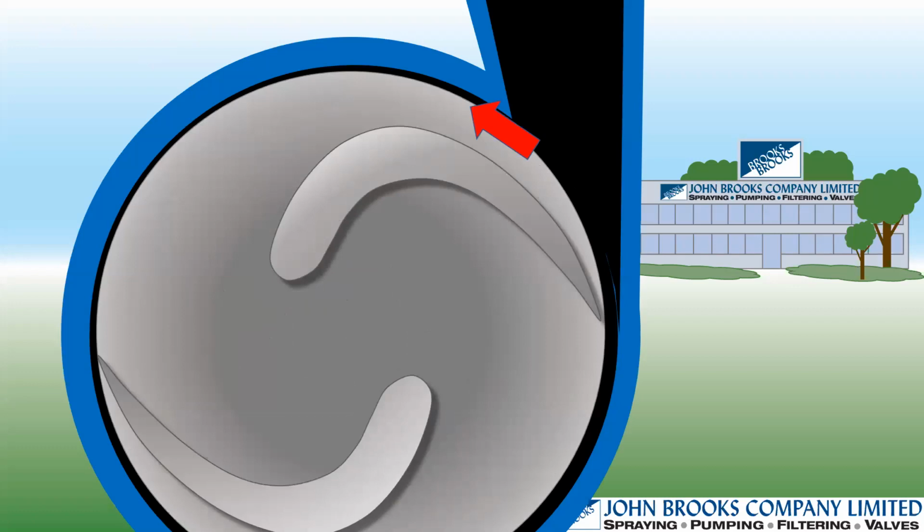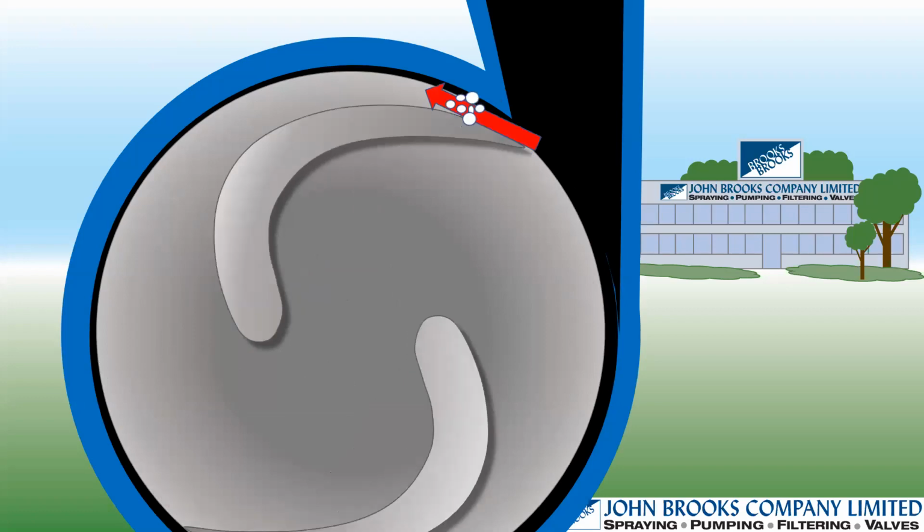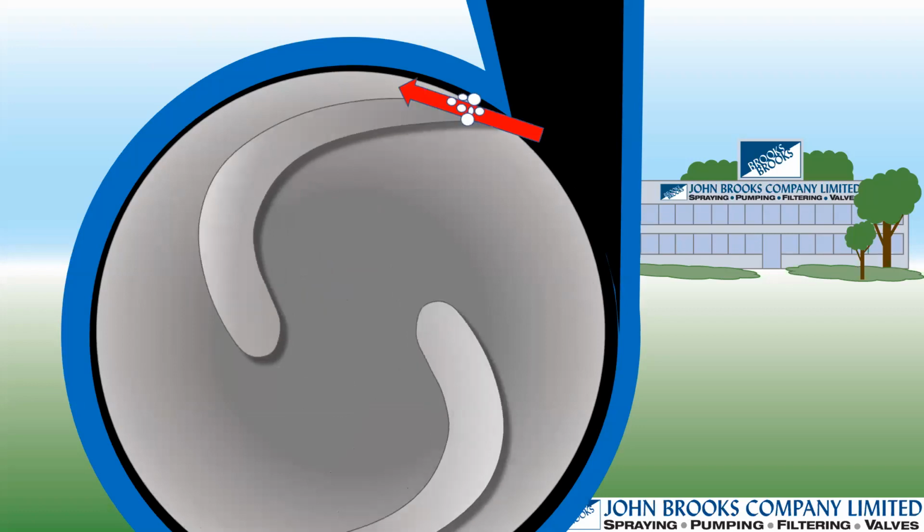We start to get this recirculation taking place between the cutwater of the volute itself, of the case, and the impeller vane. And as this impeller vane comes around, it squeezes and makes this area between the cutwater and the impeller vane really, really small. And guess what happens when we have a small area with a lot of flow traveling through it? We get some high velocities. And with high velocities, we're going to get low pressure. And we vaporize this fluid right there.